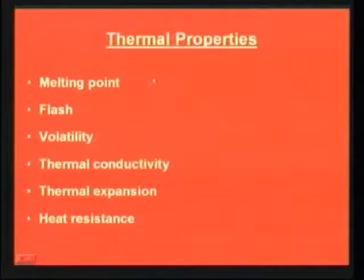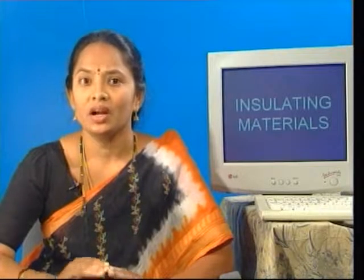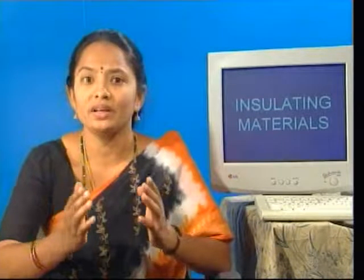Next is thermal conductivity. During operation, heat is generated due to copper losses within the conductor and dielectric losses within the insulator. The entire heat produced should be transferred to the outside atmosphere so as to maintain the operating temperatures within the limits. Hence, an insulator that is used should have very low thermal conductivity, especially in high voltage apparatus where the thickness of insulation is more.